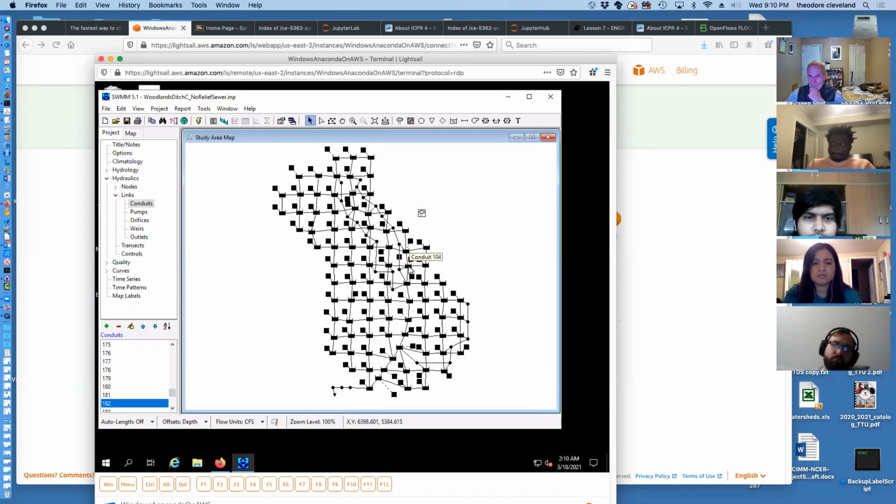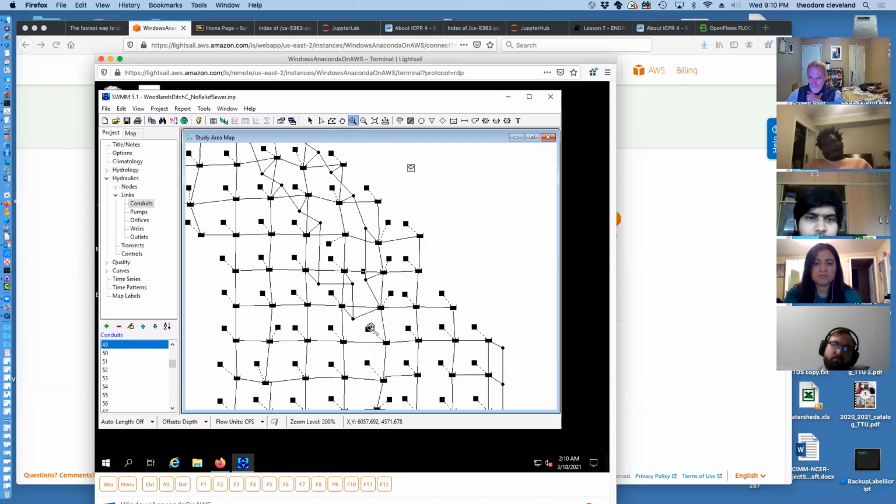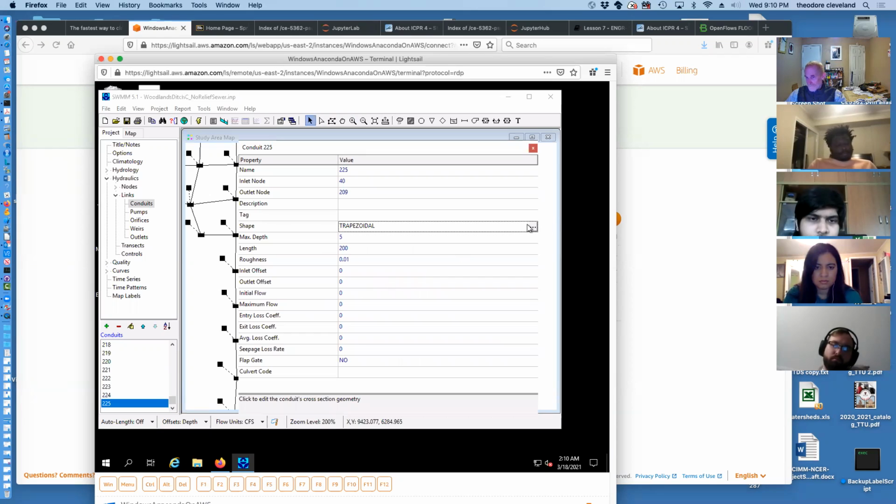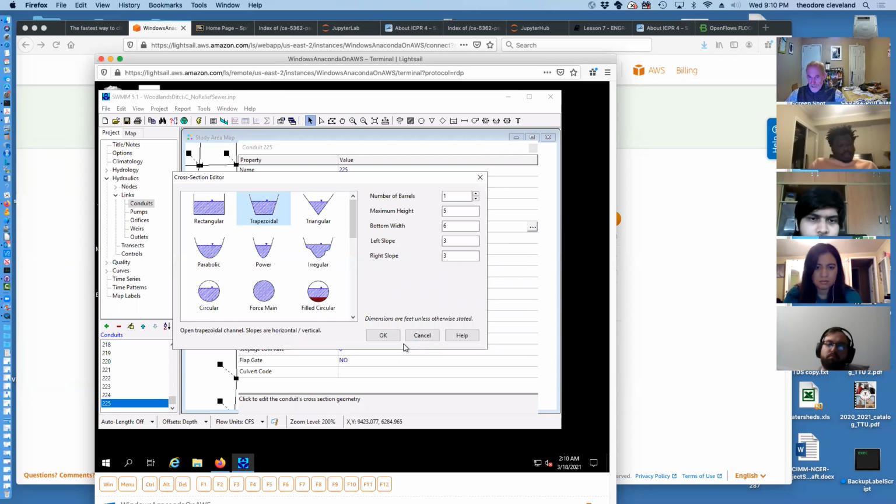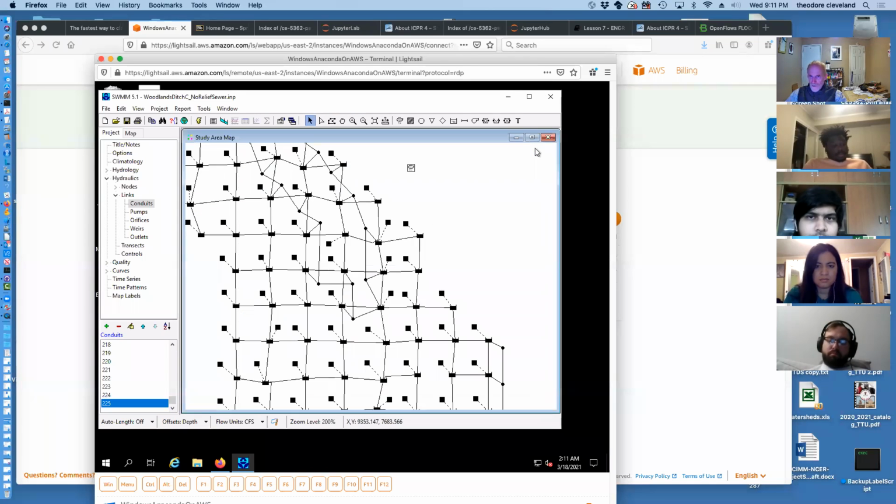it's not directly passing through a storage unit. Instead, there is a connection. There's a connection from the storage unit into the drainage ditch, and most likely this is a pipe. It's a trapezoidal channel that's carrying water into that drainage ditch. So I would suspect that on the aerial imagery, there is an obvious connector there.